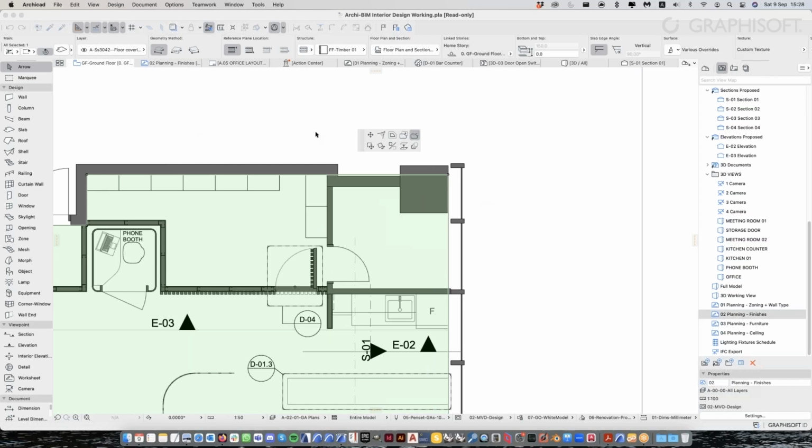So how can I draw it? I can, again, click 4 times, or since it is just a rectangle, right? I can use the second tool, rectangular method, and click 2 times, 1 time here, the other time just outside, and it will create already a rectangle.